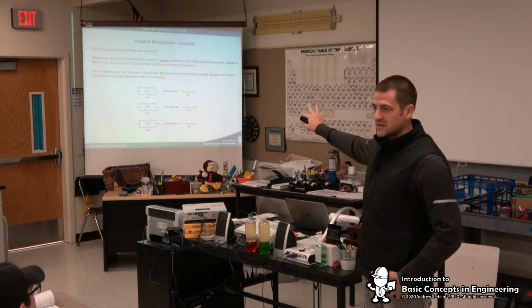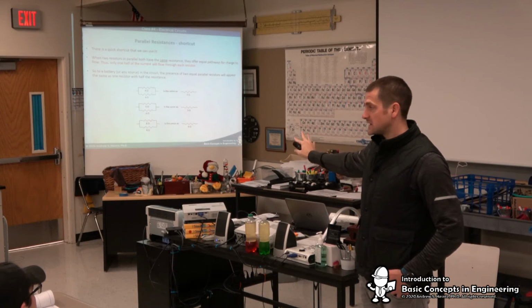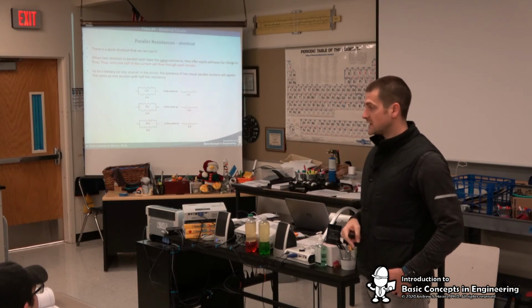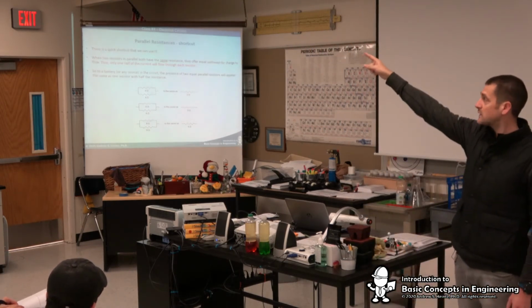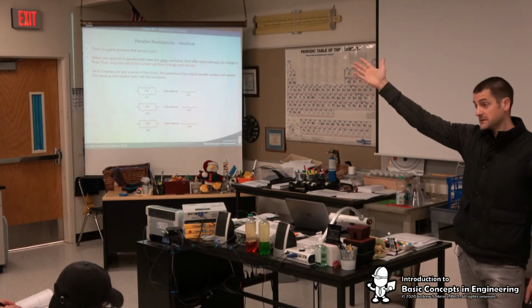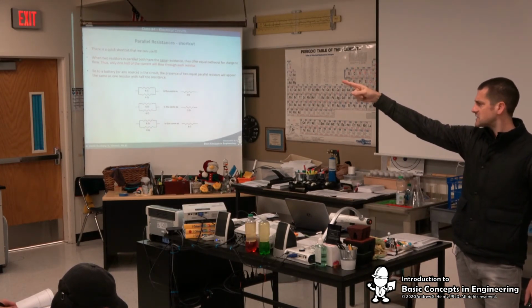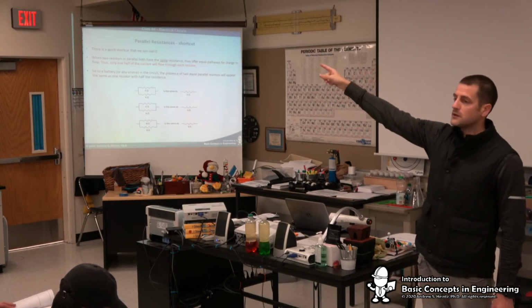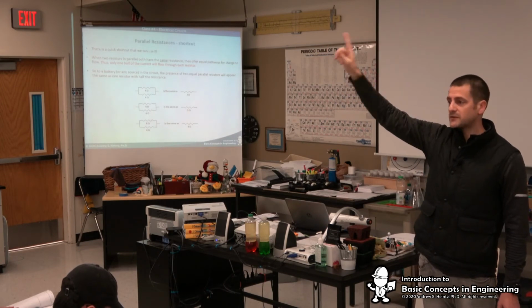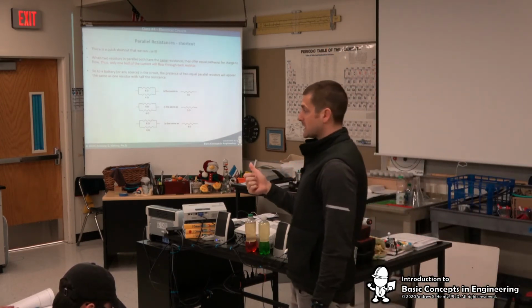But why do we see this a lot in engineering? Right? You might not in circuits class because your guy's trying to teach you something. Why do we see this a lot in engineering? Because a lot of times you're using the same lights. Bingo, and that's what I was going to point to. So these lights, if one of these lights burns out, because you guys have probably seen it around the school from place to place, I'm sure, right? I think that one's off intentionally, actually. But yes, you're correct, right? The point is, if one of these burns out, they'll keep going because these are hooked up in parallel. 1, so that if one burns out, they can keep going.